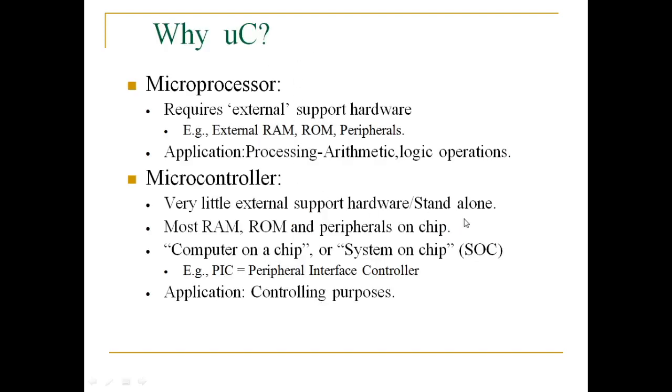So that is what I have written here. A microprocessor requires more external hardware support such as ADC, RAM, ROM, etc., so it is used for only processing kinds of applications. But a microcontroller is used for controlling applications. It requires only very little external support, because most of the peripherals such as RAM, ROM, ADC, timer, etc. are present inside the controller itself. Right. So in the market there are several kinds of microcontrollers available.